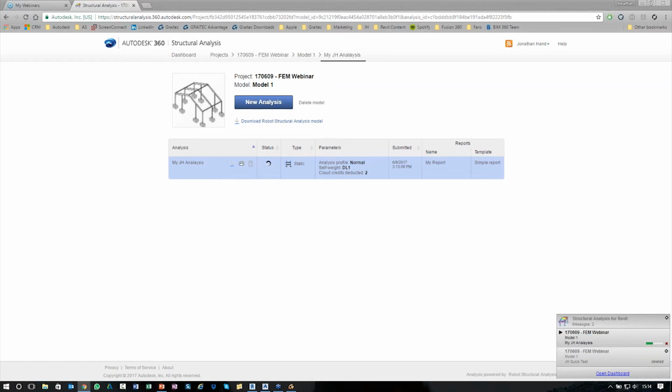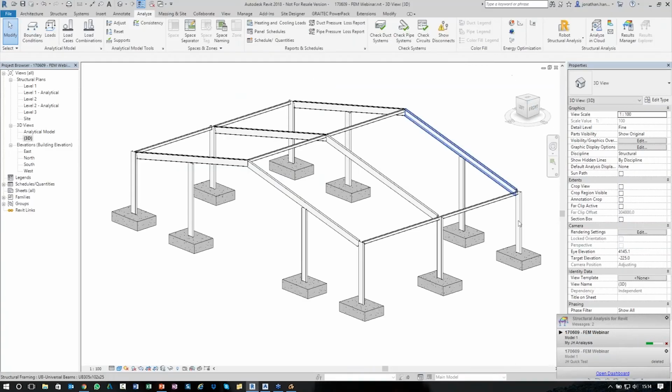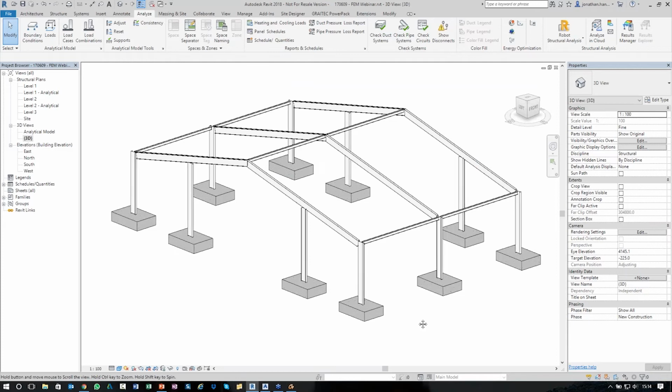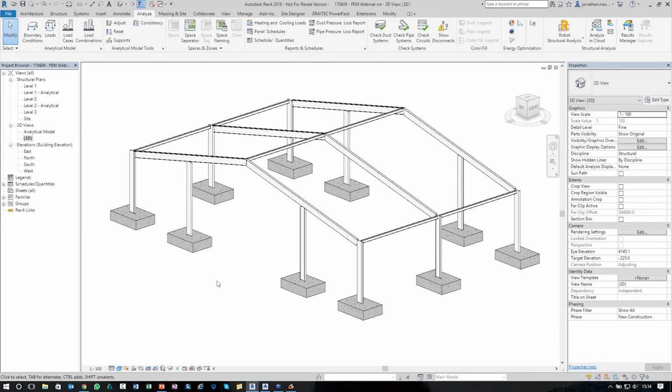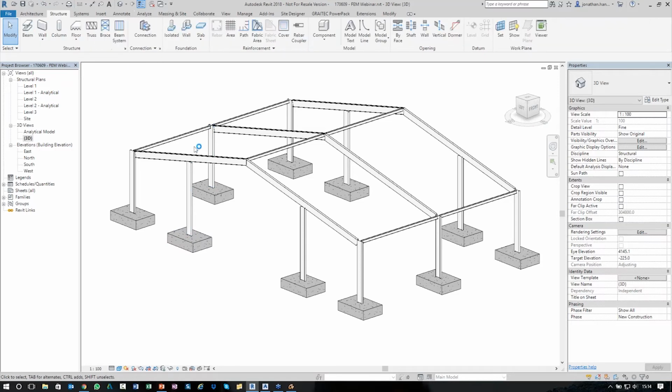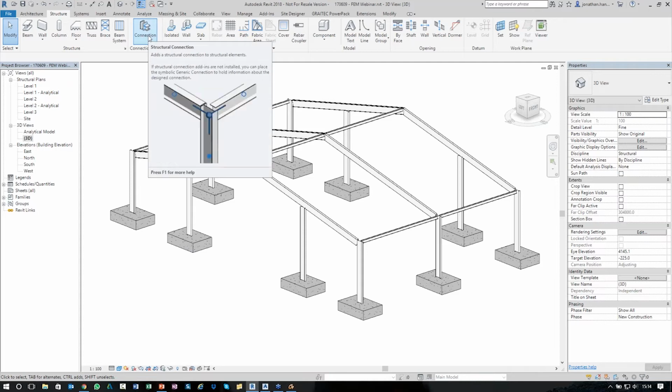So another thing about Revit, and now with it enhancing year by year, and coming in 2017, was the ability to add structural connections. And enhanced in the 2018 release is, I think, 122 connections. And these connections come from Advanced Steel. So when we look at the Advanced Steel package, we have a series of connections that come as default, and you can see the little images.